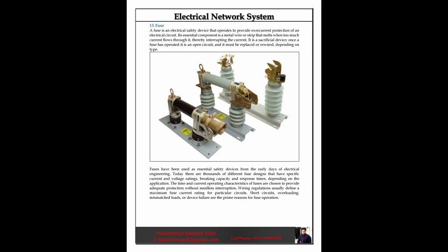Fuses have been used as essential safety devices from the early days of electrical engineering. Today there are thousands of different fuse designs that have specific current and voltage ratings, breaking capacity, and response times, depending on the application. The time and current operating characteristics of fuses are chosen to provide adequate protection without needless interruption. Wiring regulations usually define a maximum fuse current rating for particular circuits. Short circuits, overloading, mismatched loads, or device failure are the prime reasons for fuse operation.